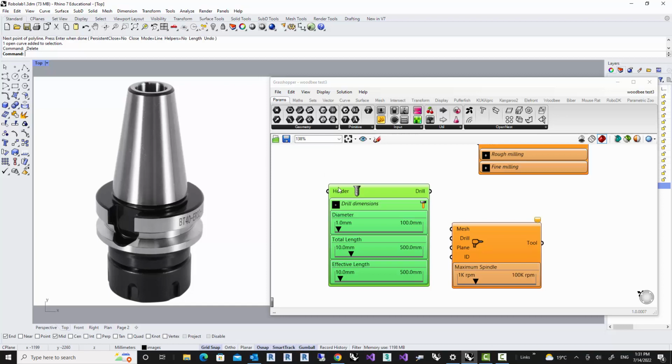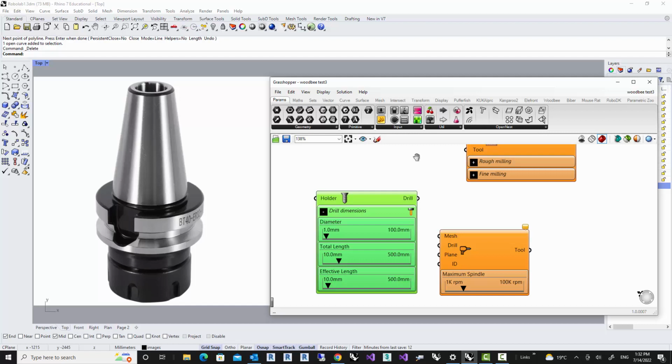And what we need to do here, because this component just accepts a bunch of numbers, we need to provide the coordinates, 2D coordinates of the points on the profile that are important. And this geometry is used for collision detection, so it's going to change some of these milling strategies later on here. So they really depend on the tool holder at some point. And it also shows in the preview, so we can see how the tool moves on the toolpath.